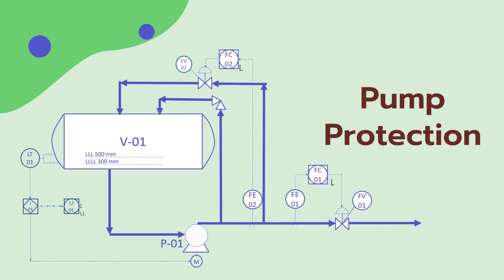For the above reasons, it's common to install protection against low pump flow, and sometimes against high pressure in case of using a reciprocating pump. Depending on minimum flow control is not sufficient in many cases. This is because we may need another layer of protection in case the control loop failed. This can be subject to further studies during HAZOP and SIL analyses.